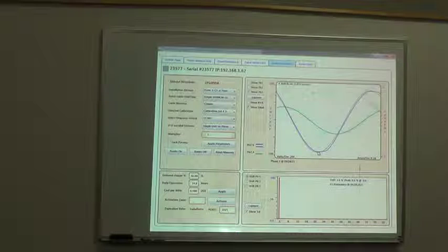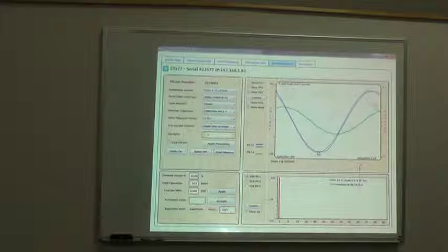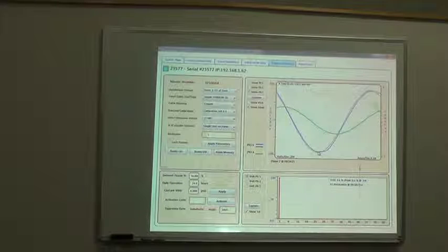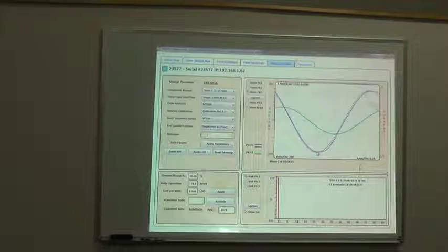Power factor as we measure it is theoretically only valid if you have a perfect sine wave. If you don't have a perfect sine wave, then exactly what frequency do you use to calculate it? You don't have a reference. Imagine if your harmonics were 50%, right?